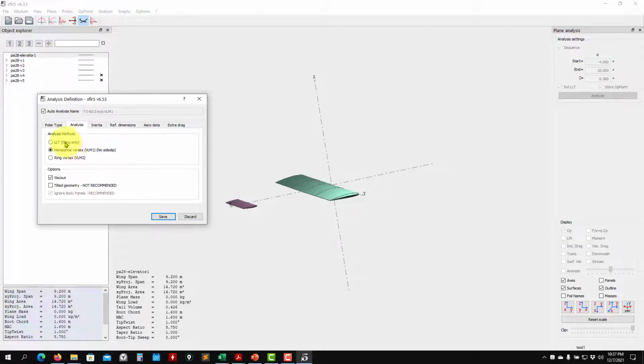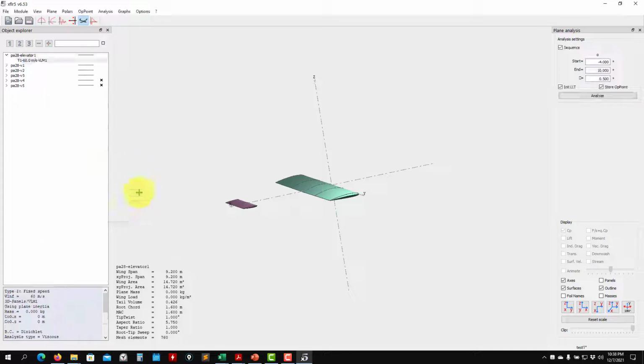This one is only for the wing. So here you have the comment. To run this one, we choose one of these methods. In my case I use the BL1, and we run the previous airfoil just to get the viscous data, because I want to do that correction also, but it is recommended not to. If you disable this, it doesn't matter, you don't need the viscous data, but let's enable that, and that's all. So you press run and it will run the simulation.